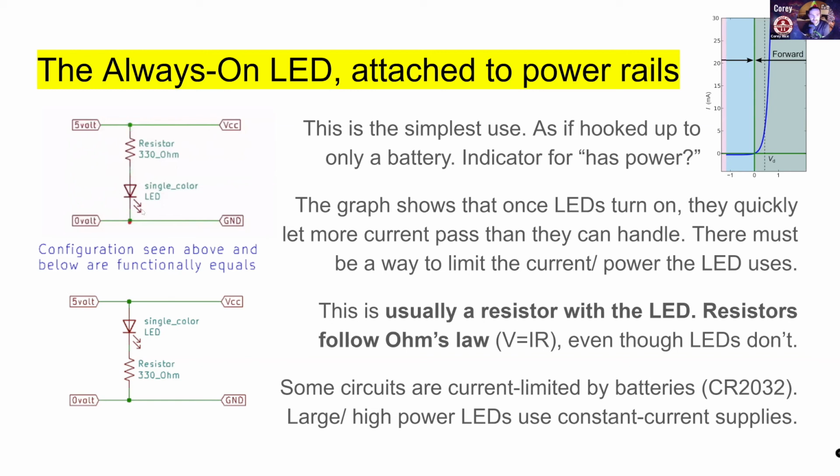And that means that you want to have the cathode, which is the shorter lead all the time, be the one that's attached to the ground pin. That's the negative, right? Yeah, the negative one is attached to the ground pin, and ground is sort of like the negative side of the battery. So they're trying to help with that.